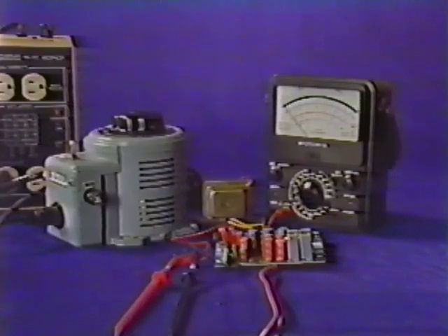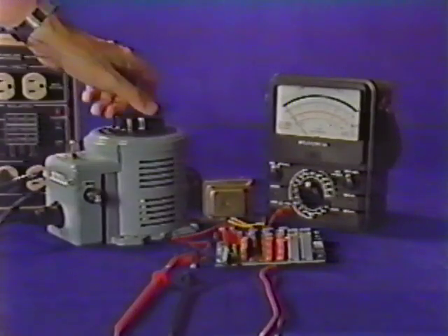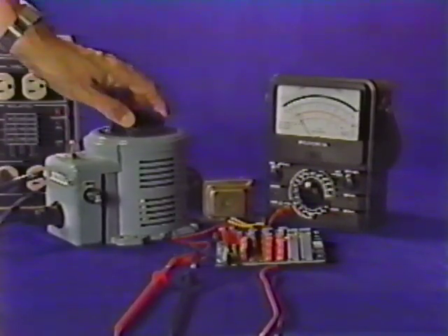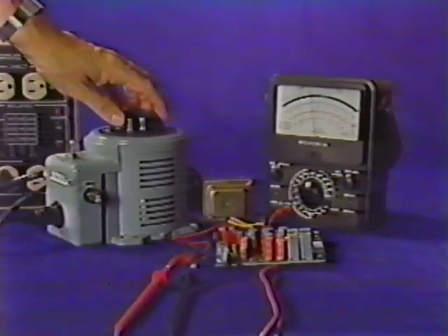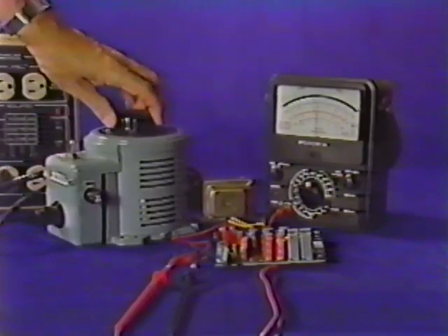If these techniques do not point to the source of the problem, connect the supply's line input to a variac. Adjust the variac to produce about 30 volts and observe the system. If the fuse does not blow, measure each power supply output and check the load circuits for the first signs of improper operation or overheating.